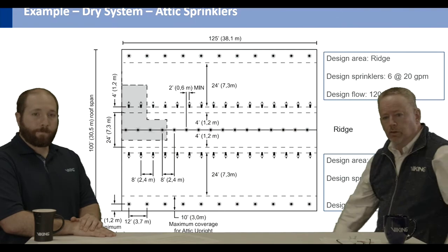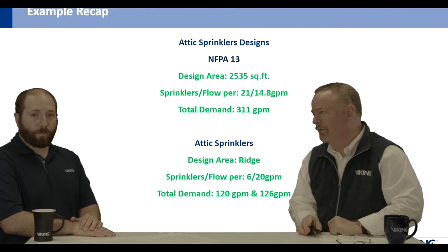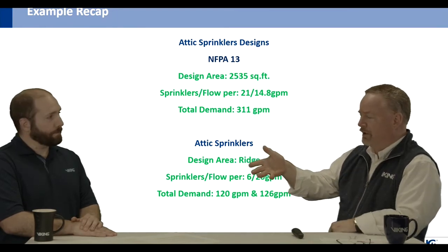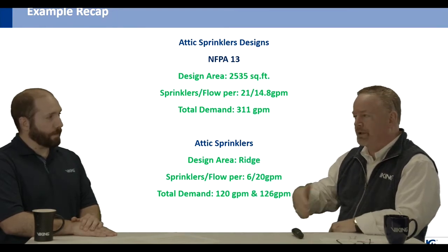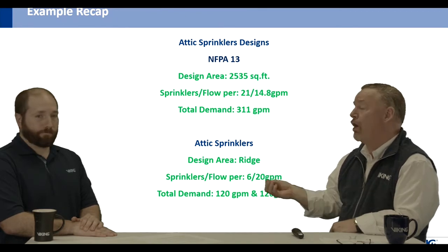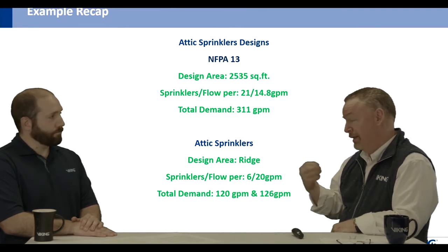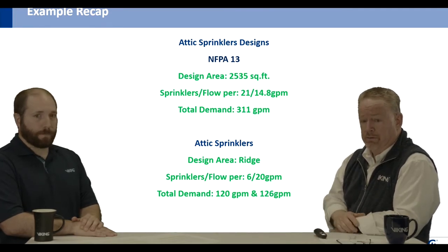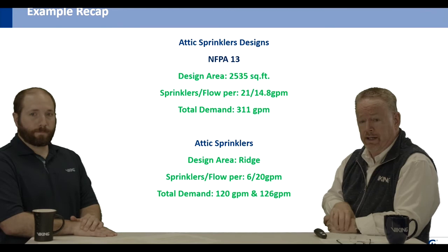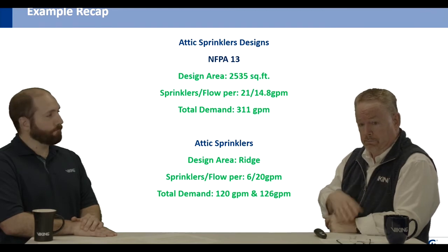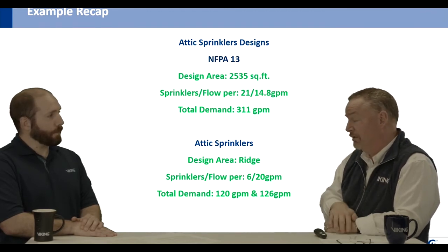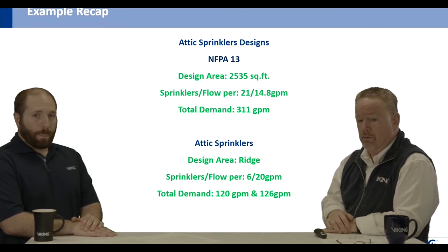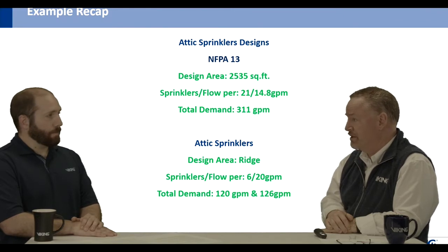Okay. So given that, here's basically the totals that you wind up with. If you do the NFPA 13 design with just standard spray sprinklers, you wind up with not only more water, but a lot more pipe and a lot more installation costs going into it, as opposed to this lower flow design, with a lesser number of sprinklers actually flowing. Correct. It's a great savings, more than 50% on the demand of the system.